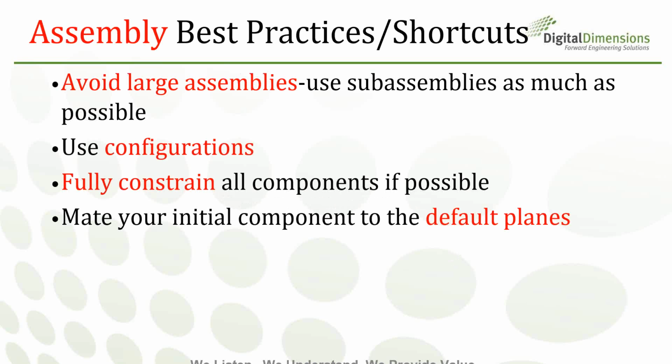Mate your initial components to the default planes. This is a good one. This is just a personal preference of mine, and it also makes for good design practices whenever you're building an assembly off of an individual component: mating your individual components to the actual assembly planes themselves. I'm going to show a few cool little options with this.